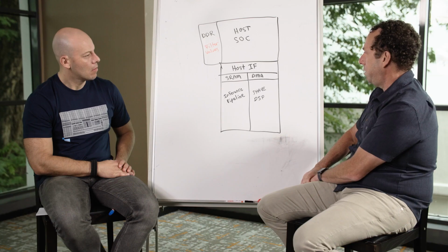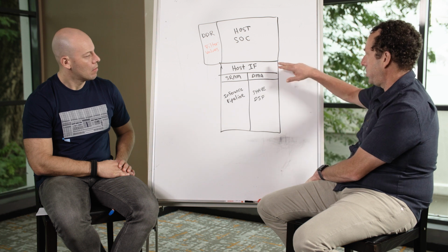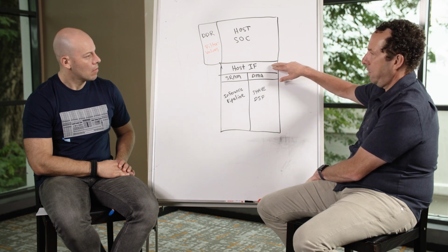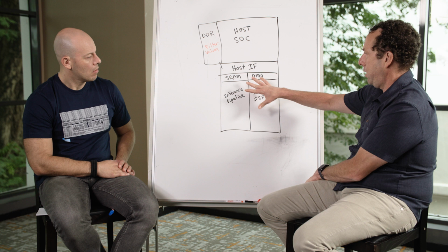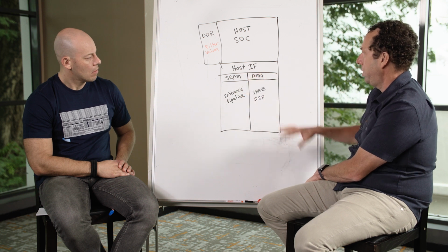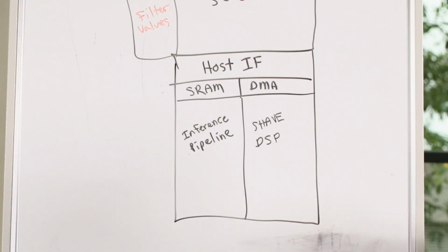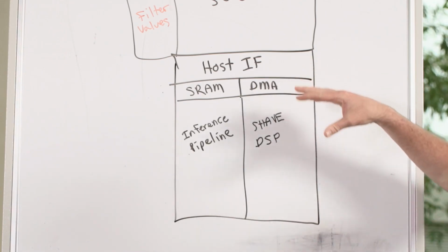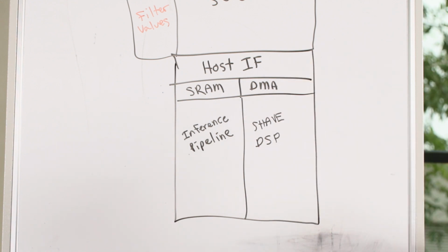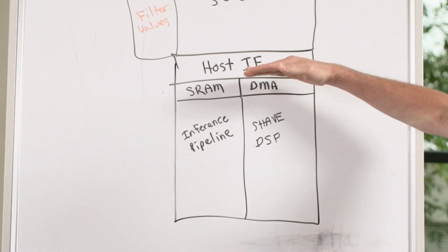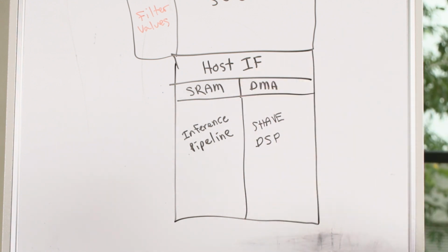So we basically have two components. One is, let's say, the host interface and the control for the NPU, and then the rest is the compute portion. The host interface portion communicates with the host that does all the scheduling and memory management. The host interface also controls the scheduling on the device, power management, those kinds of things. And then everything below here is compute.